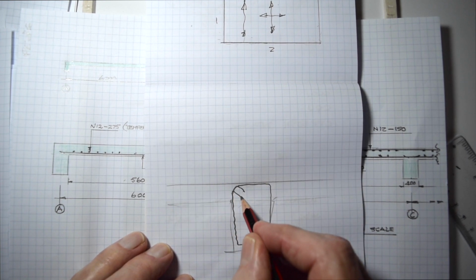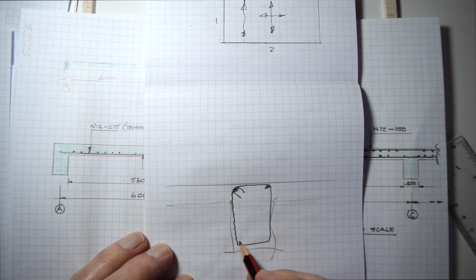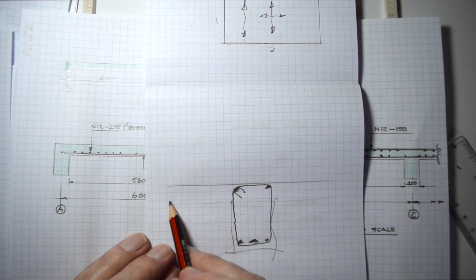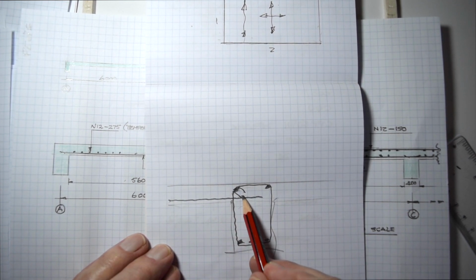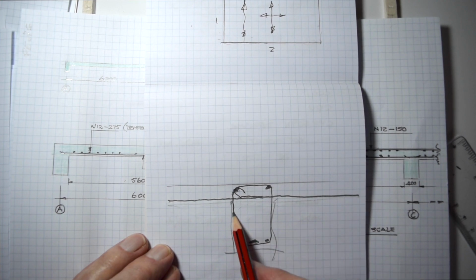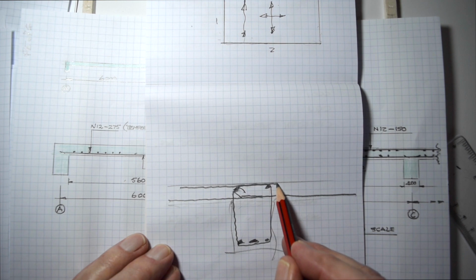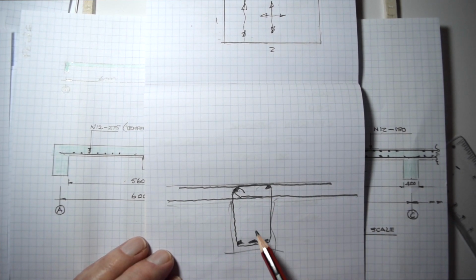You've got your ligatures, two tie bars there, maybe lightweight tie bars, N12s, N28s or whatever. Then you've got your main slab steel coming through to there, and the other one for this span runs through there. You've got your negative steel, the negative moment, resting on top of that. That's how it's fixed. It's tied onto those ligatures.